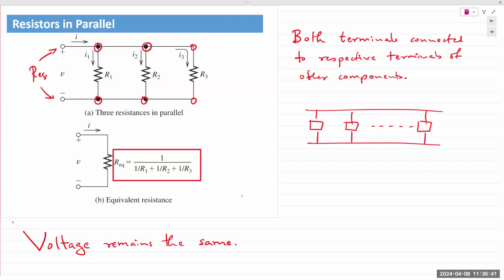Yes. That is very good. Yeah. So the question being asked is, if we wish to measure the individual resistances in the connection, would we have to disconnect? The answer is yes. We would have to disconnect. And taking it one step further, this goes into the next slide. So actually two more slides. If we have a source connected to a circuit, you have to disconnect the source before you measure your resistance. This is the actual practical equivalent.